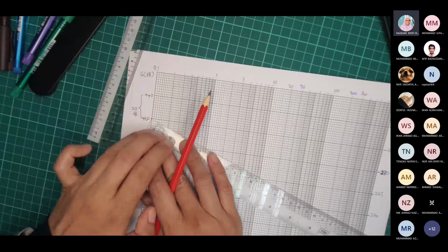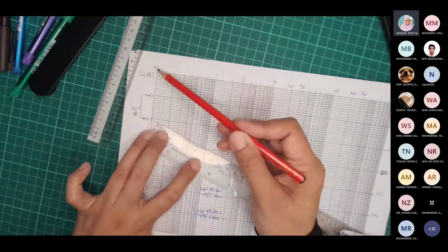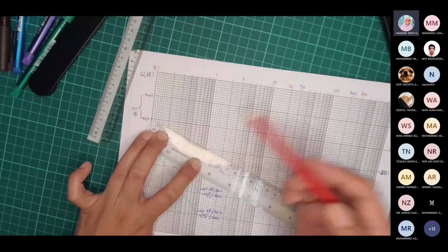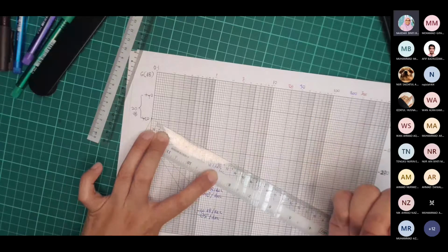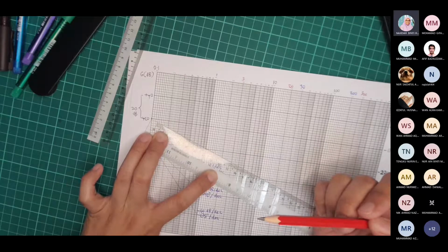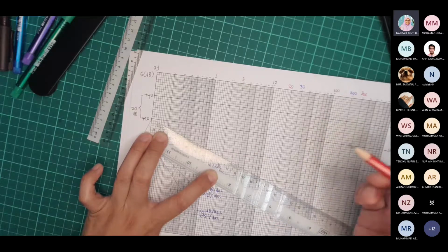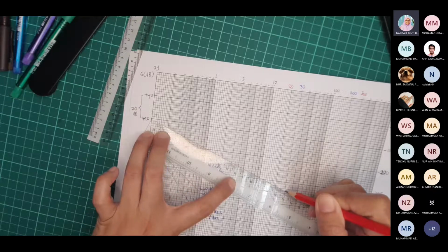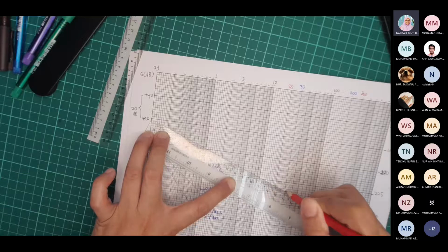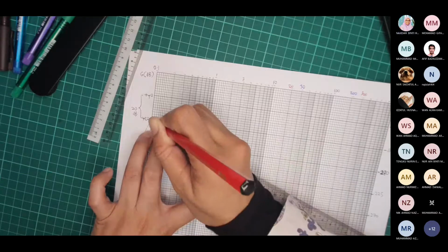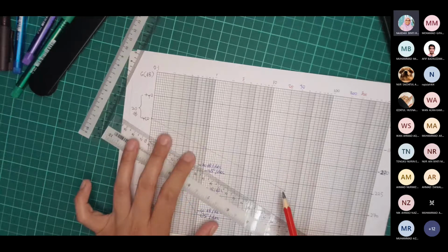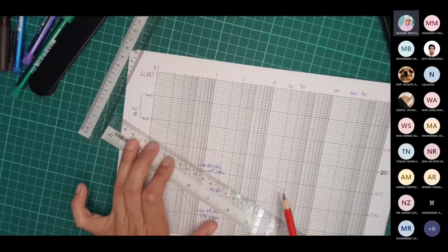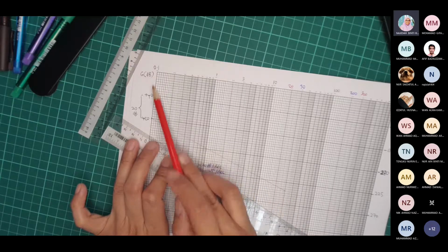Now I want to sketch from 0.1 until 30. So this one is negative 20 dB per decade. Since we want to sketch negative 20 dB per decade from 0.1 until 30, I suggest students start at 30 radian per second, where you want to stop this negative 20 dB per decade. Start from here until 0.1. So this is my first part of the magnitude plot, negative 20 dB per decade from 0.1 until 30.